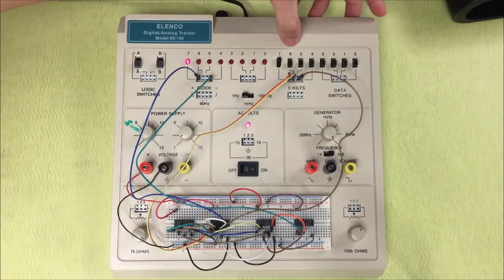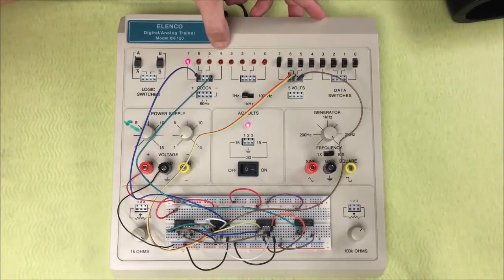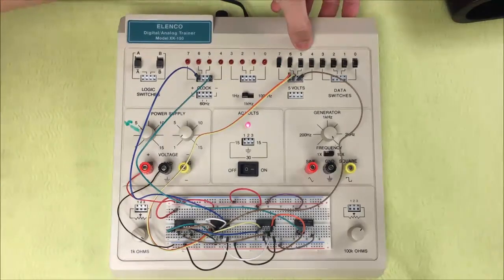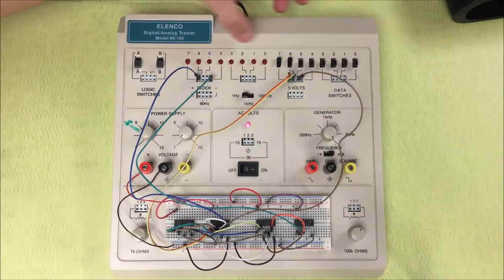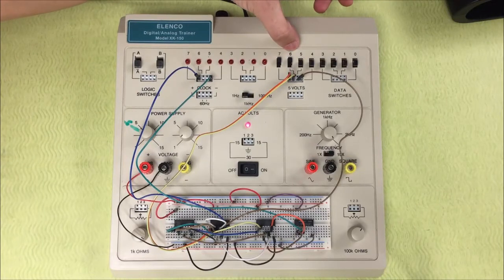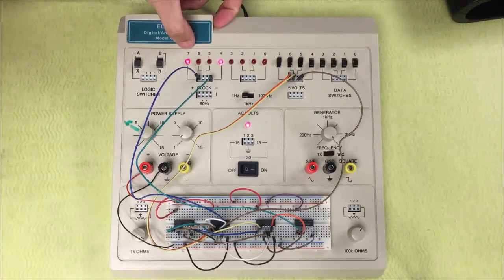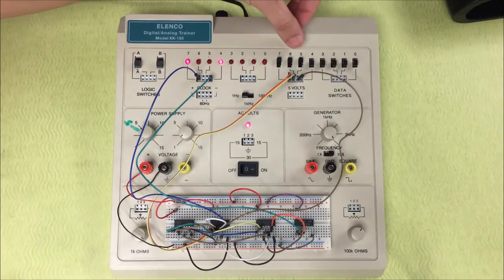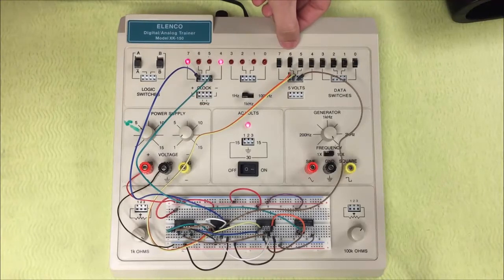When we make X equal 1, Y equals 0, and Z equals 0, then 1 minus 0 is 1 with borrow 0. When X equals 1, Y equals 1, and Z equals 0, then 1 minus 1 is 0 with borrow 0. When X equals 1, Y equals 1, and Z equals 1, then 1 minus 2 is 1 with borrow 1. Similarly, you can check all the other possible combinations and verify your truth table.